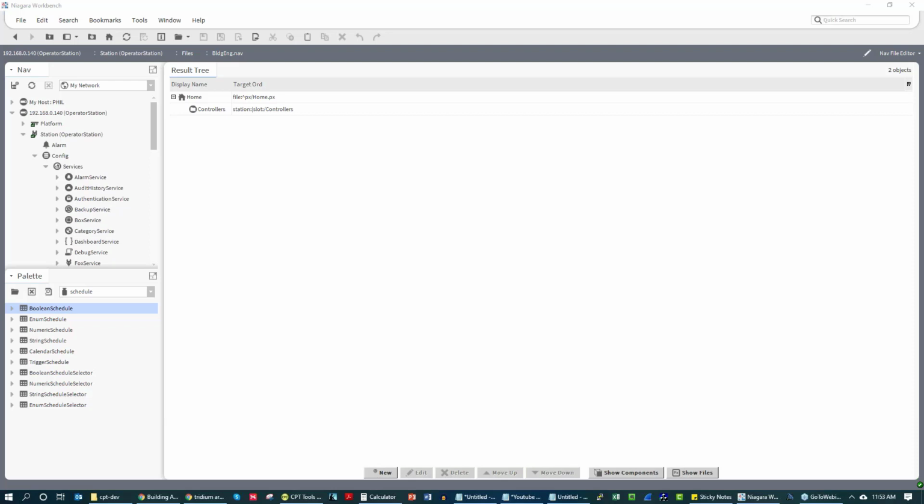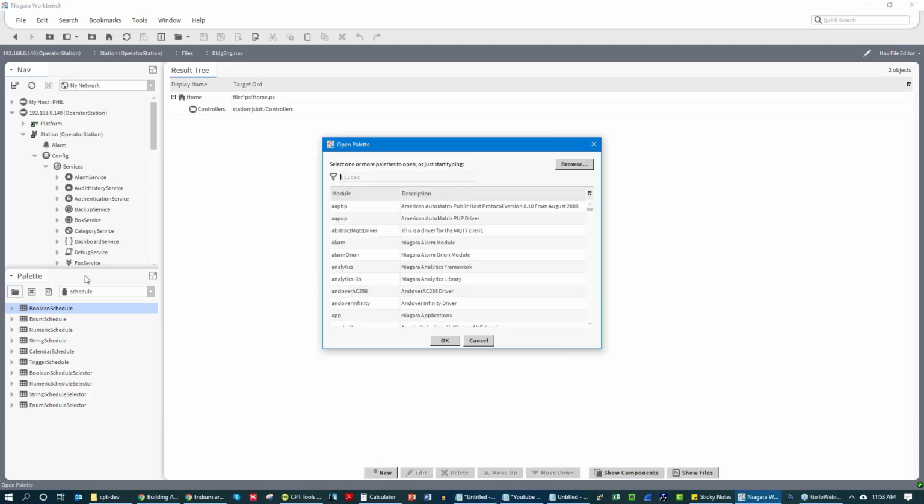All right, so Tony asks, can I add Modbus points to a Niagara interface to monitor BAS efficiency electrical meters? Yes, you can. Right there, Modbus. You would just add the Modbus driver, you would pull it under the drivers, and then you would map it in. So there you go.